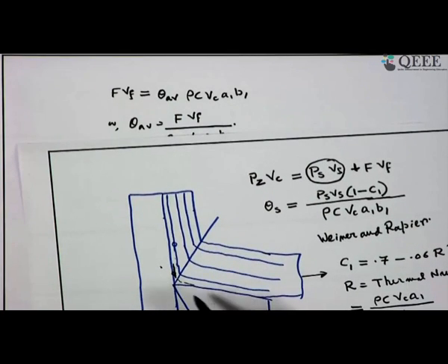However, here we can see that this temperature will vary depending upon the conductivity, because it is also known in theory that, because of the conductivity, the temperature is never highest in this zone; rather, the temperature is highest at a distance away from the cutting edge.